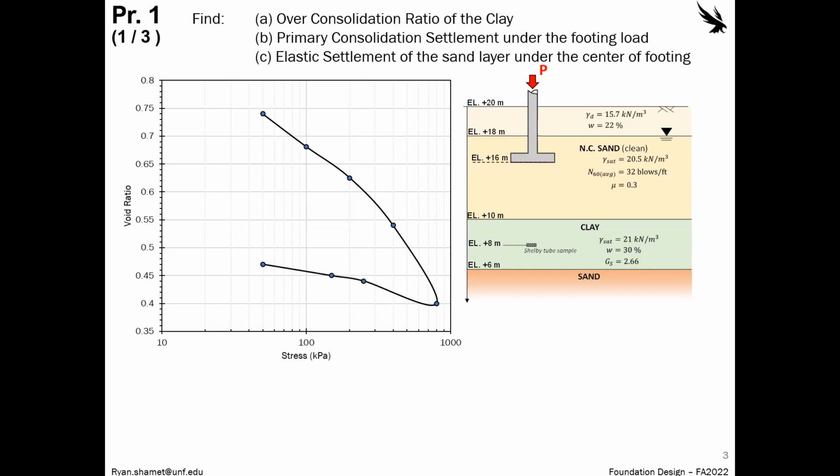If you remember, using the Casagrande method you first look for the point of maximum curvature, the point at which the curve curves the most, where the trend line changes. Then you go through that whole fun process of intersecting, drawing the straight lines, and bisecting angles, and you can find your sigma C, which is your pre-consolidation pressure.